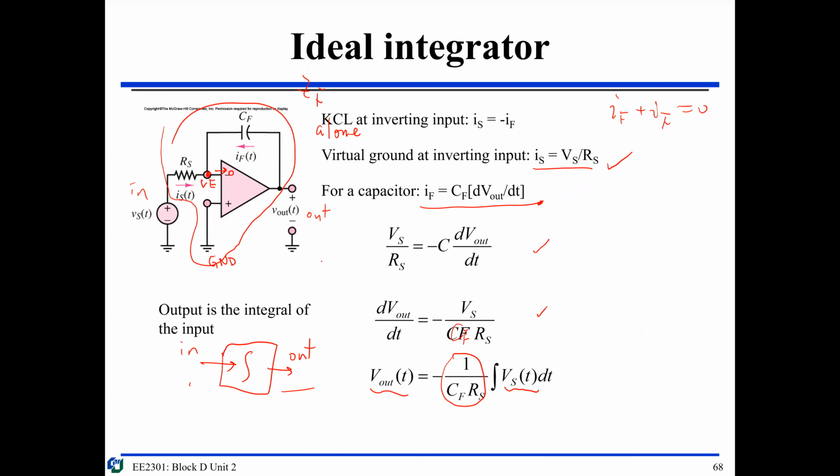Similarly, going back to the integrator, you have something like this. This is the magnitude of 1 over j omega, so you also have minus 20 dB per decade, and it always goes way up. The lower the frequency, the higher the magnitude.